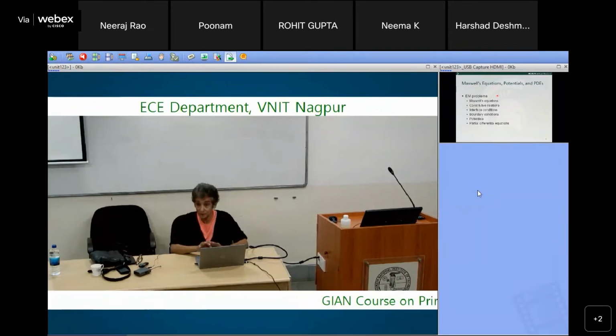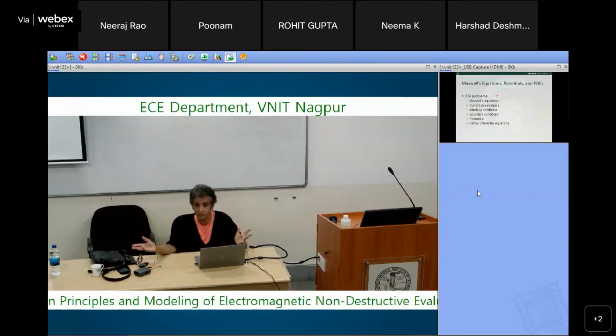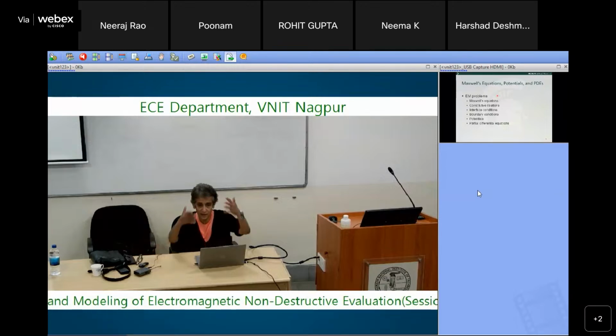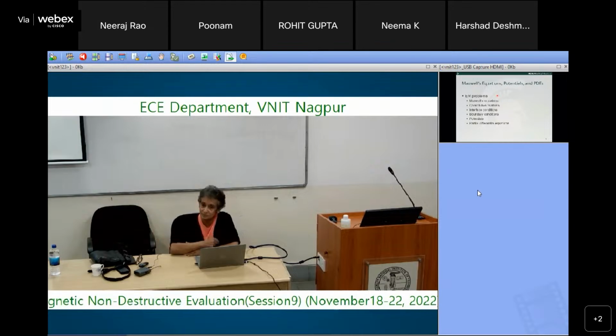At the input, you give the signals, different signals, and in the output, you have the corresponding defect profile, and you let the neural network learn that mapping function. And then you have a test signal, it will tell you what the defect profile is.